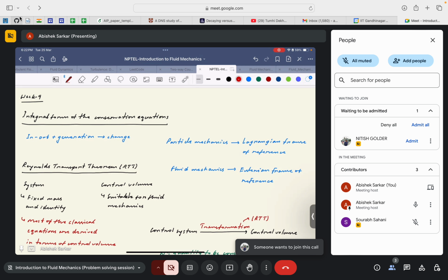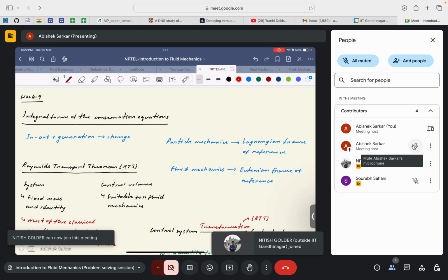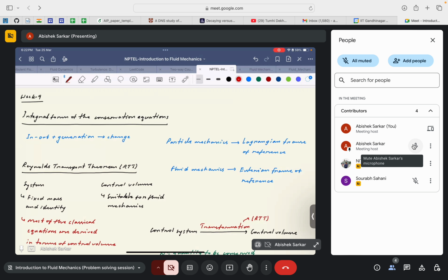essentially analyze the fluid flows as inviscid flows, because most of the fluid flows that we see around us are viscous, but since the viscous effects are quite limited to a very small region in the boundary layer, most of the regional fluid flow can be taken as essentially inviscid. But again, remember that the flow is not inviscid because the viscosity is zero, but the velocity gradients are too small to manifest any kind of shear stresses in the flow field.